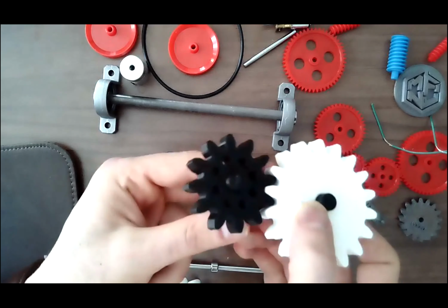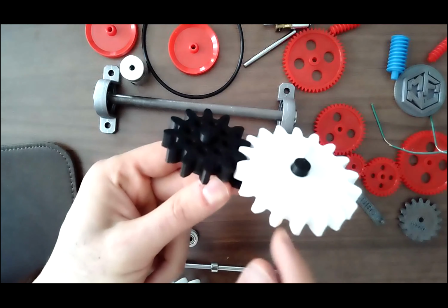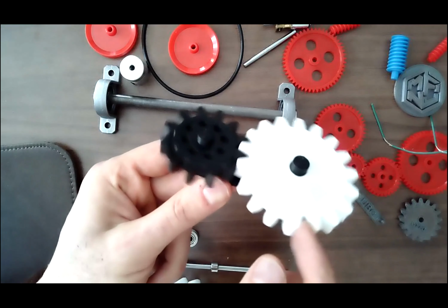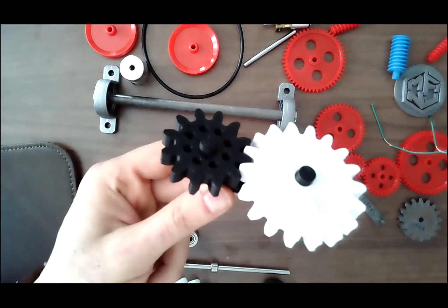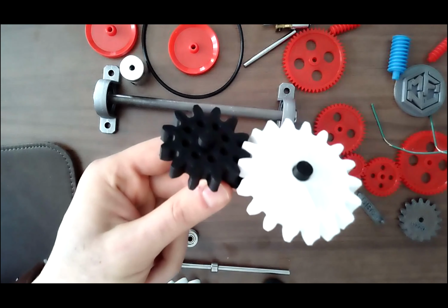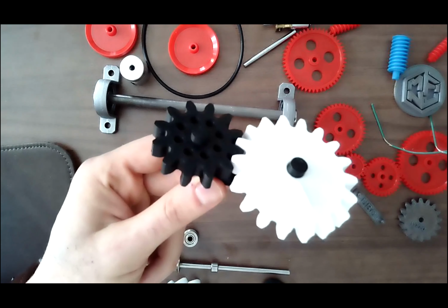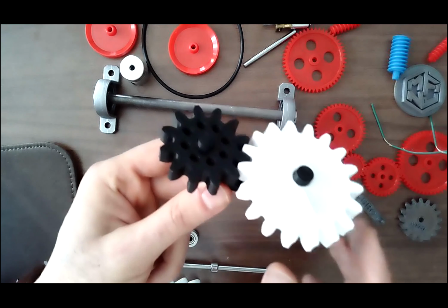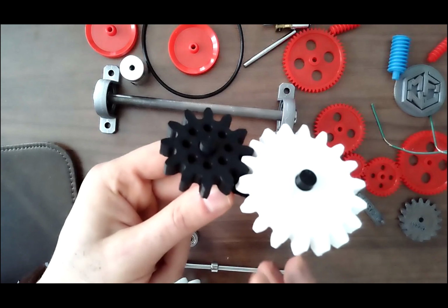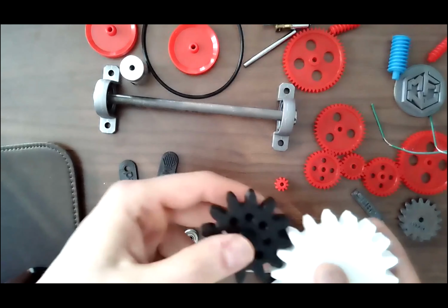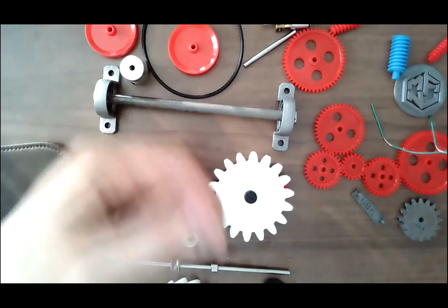My motor can be attached here. So if I rotate it, the black one now rotates faster, but it's going to give me a smaller amount of torque. Remember, always the power is going to stay the same. And the power, if you recall, was T torque multiplied by omega, right? T multiplied by omega. So if one of them increases, the other one decreases, because we assume the power always stays the same. Conservation of energy.